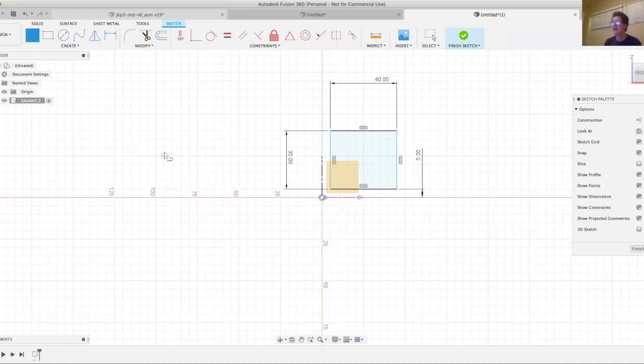So with the line tool, a few things happen. One is you see a certain level of snap. We're going to do another class on detailed sketching, because sketching is really important. But one of the things that Fusion 360 does that's interesting is you can specify your snap by a specific amount, or you can let it do its own intuitive snap grid.